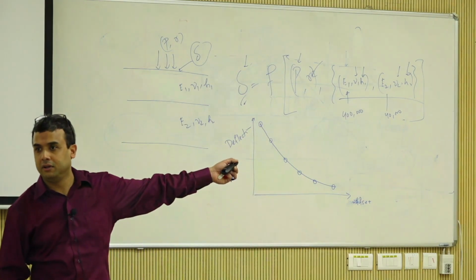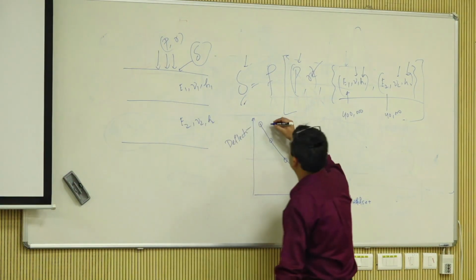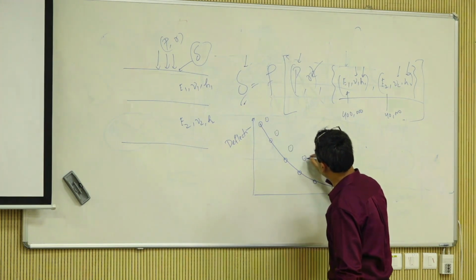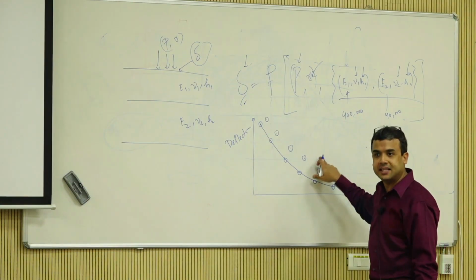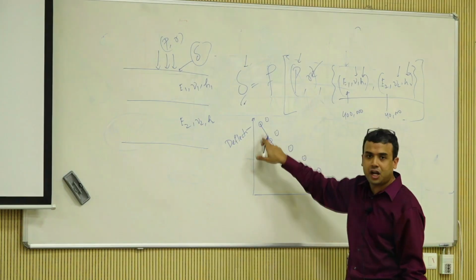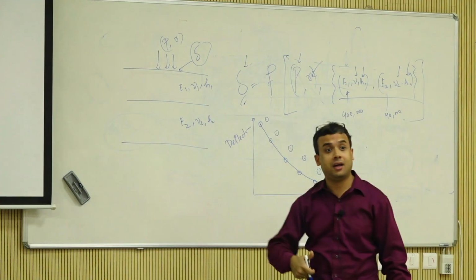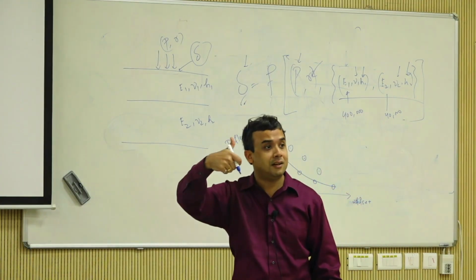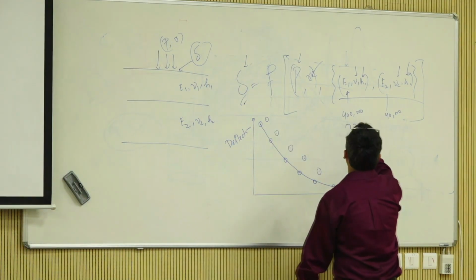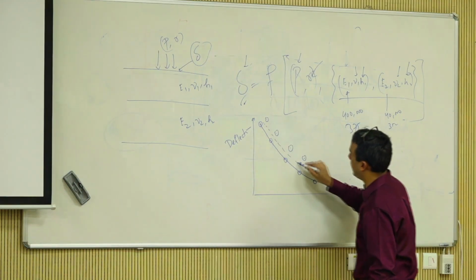when I used 400,000 and 40,000, right? But then you go and run an FWD and you find that the basin actually in the field looks like this. So what did I just do? I under predicted deflection, so I overestimated E. So I should be reducing the E somehow. So maybe I should make it 75, maybe make it 35, something, try to make another line.